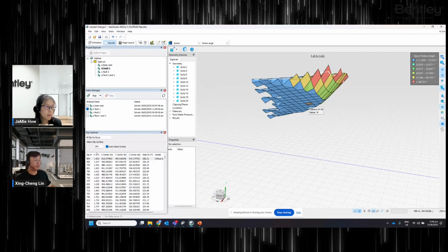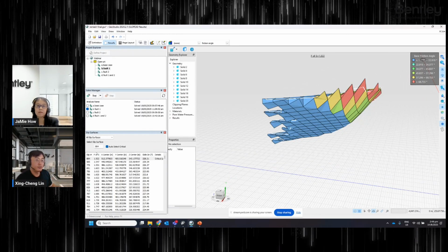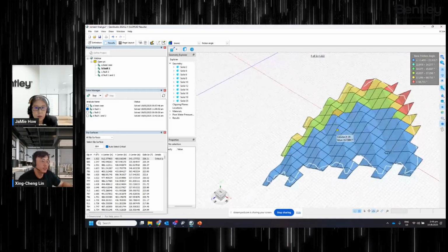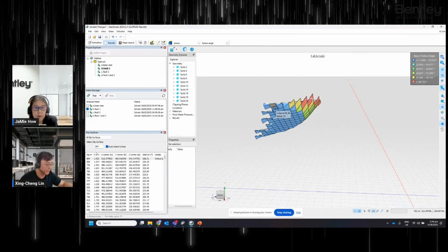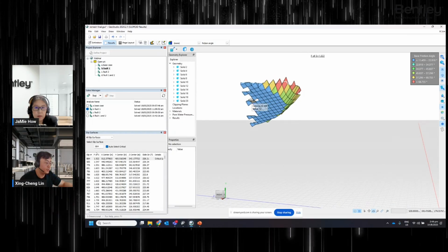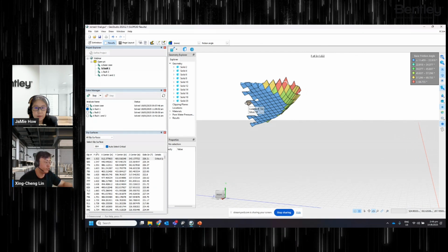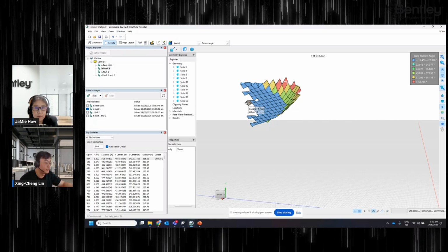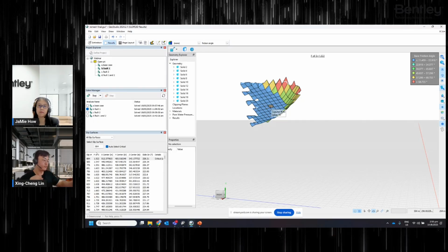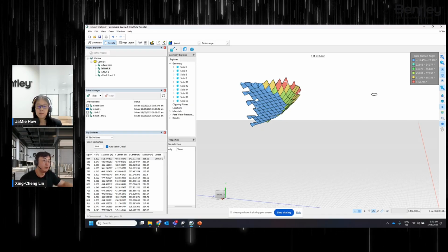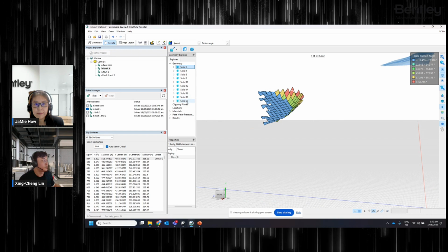So clearly, remember the friction angle for the wedge surface that we have defined is 14 degrees, which is here, the blue colors. These are the friction angle at the base of this sliding mass, just in case B. If you look at this kind of heat map, you actually get an idea of what materials are actually involved in the entire sliding mass. You can see that the columns right here in blue are apparently truncated by the weak layer that we have introduced as fault number one. Therefore, we have a reduced friction angle. If you look at the legend, there's 14 for the blue area.